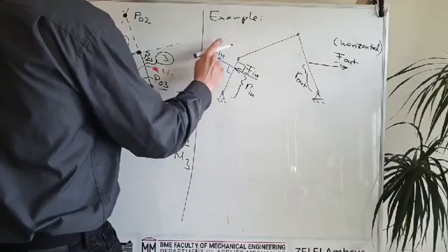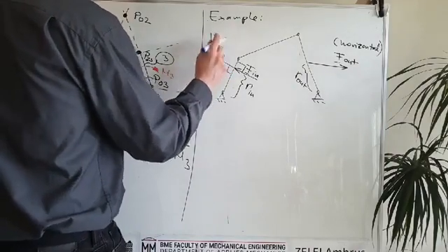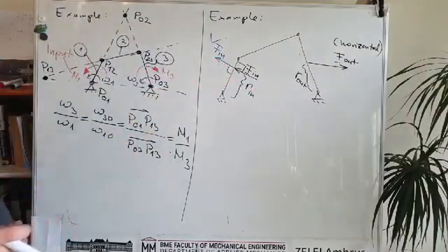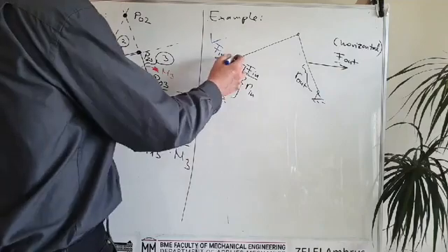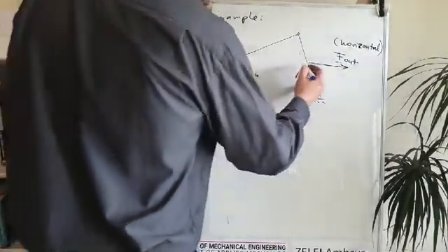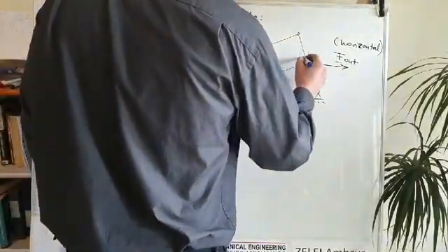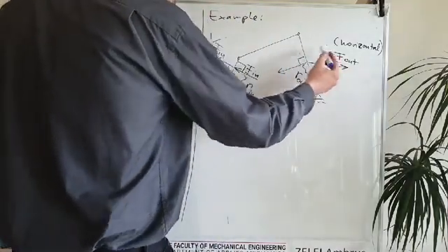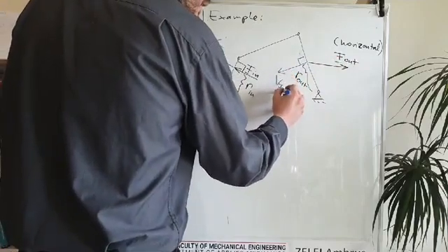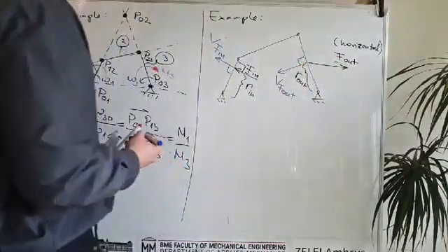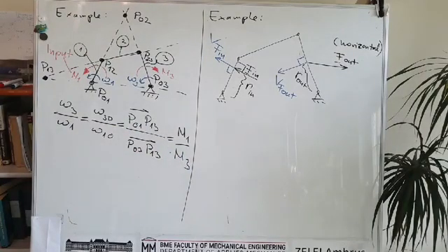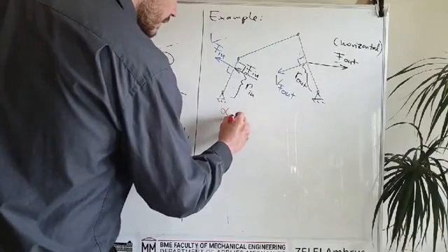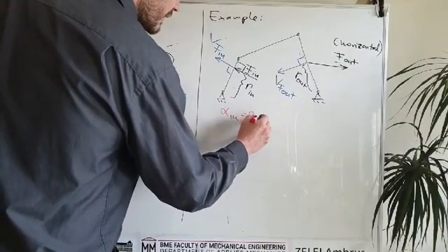This is Vf in, the velocity of the point where the input force acts, and this is also perpendicular to the bar. Here the output velocity is perpendicular to the bar, but now it is not in a straight line, it's not collinear with the output force, so the cosine alpha will not be zero here. But here we see that the alpha input is always 90 degrees, right?